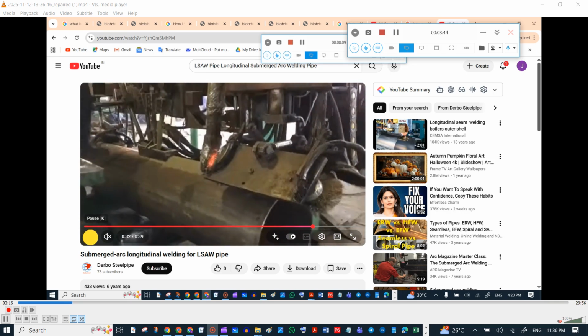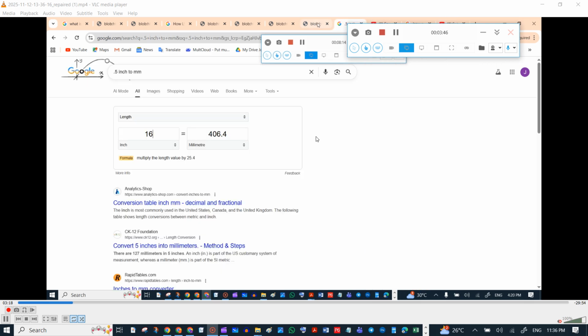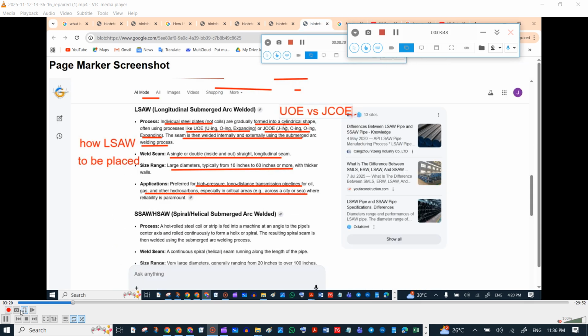It's a video of submerged arc welding. The next one is LSAW, longitudinal submerged arc weld. Here individual steel plates are used, not coils. It is gradually formed into a cylindrical shape using the UOE method or the JCOE method, meaning J-ing, C-ing, O-ing and expanding.